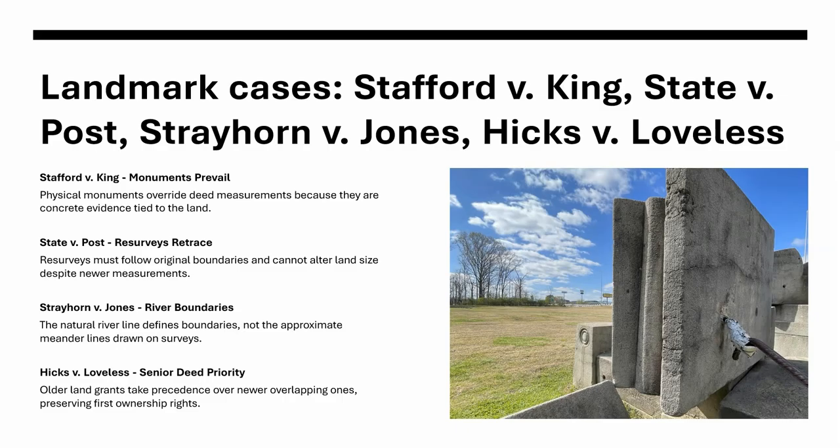Resurveys retrace, they do not redesign. The job of the resurveyor is not to redraw the land according to new math. It is to follow the footsteps of the original surveyor, to locate the boundaries as they were originally marked. Even if the original measurements were imperfect, the physical monumentation is what defines the land.